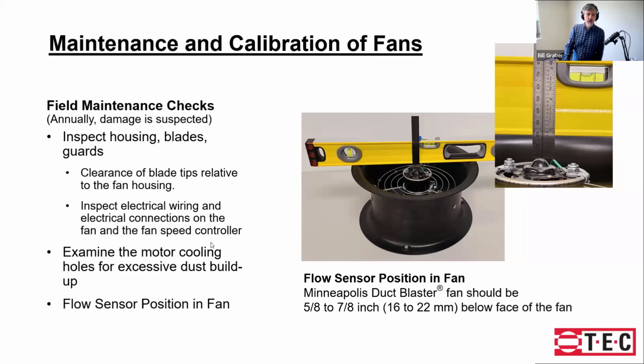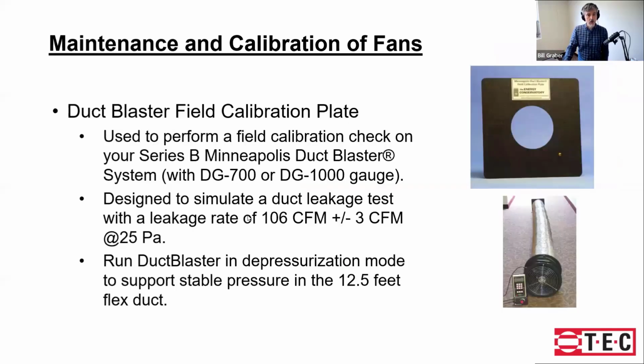We used to say, check to see that the sensor on a duct blaster isn't leaky like we do on a blower door, which we continue to do. On the duct blaster, we no longer recommend that. This is a brazed sensor. Even if you drop a fan, that is not something that's going to be damaged. And we've had people get false diagnostics that, oh, I might have a leaky sensor, when in fact, it's just a challenge of sealing the smaller sensing holes in the sensor. So that's been updated and we no longer do that.